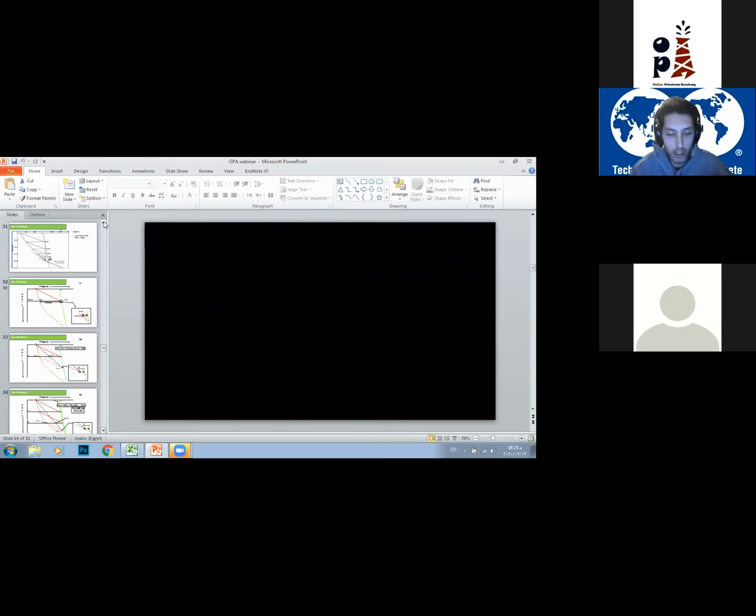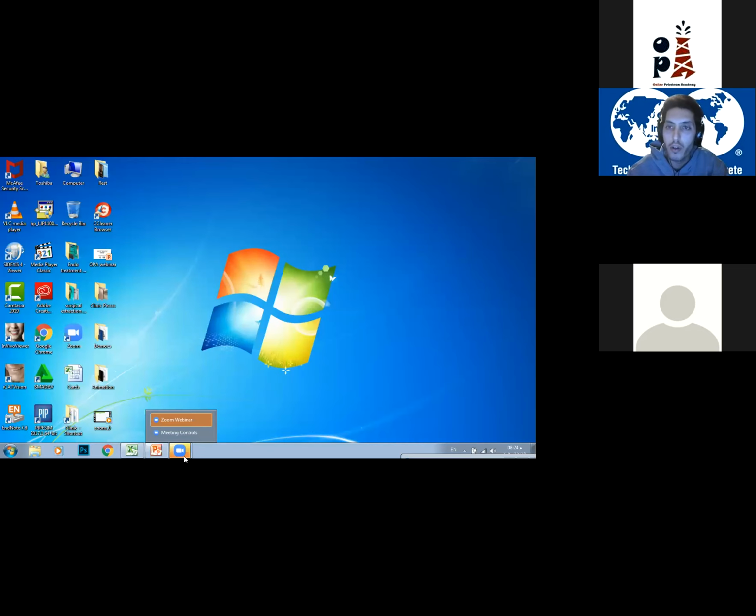And before you explain, I can show this for people who can see. This is a valve, if you can see it. This is a gas lift valve that, as Engineer Ahmed said, was taken from a well because it's not working. It's a well intervention with a slickline or a wireline, because we have several questions about that. But you do it only if you have a problem, because you may have to stop the production and other things. So, Ahmed, if you could answer why we have many valves and at which depths.